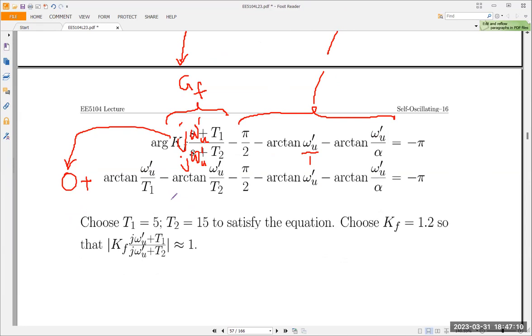Normally we try to choose T1 and T2 as close to each other as possible such that they satisfy this equation. That is classical control, which you will learn when you first do control engineering. As far as I'm concerned, just choose any T1, T2 that satisfy this equation, and try to make them as close to one another as possible. That's it, this is a design problem.